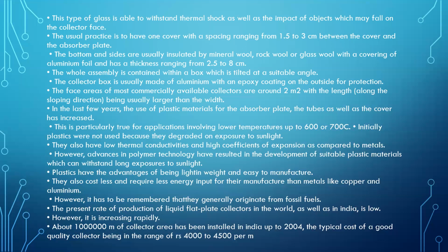The face areas of most commercially available collectors are around 2 square meters, with the length usually larger than the width. In the last few years, the use of plastic materials for the absorber plate, the tubes as well as the cover has increased. This is particularly true for applications involving lower temperatures, up to 60 or 70 degrees Celsius.